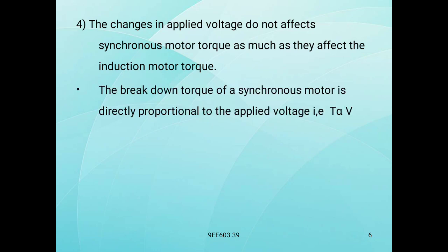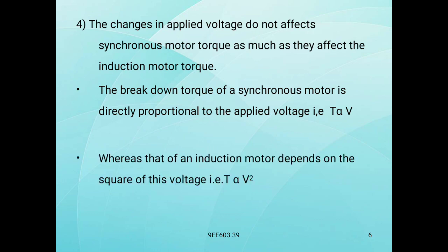The breakdown torque of a synchronous motor is directly proportional to the applied voltage, that is, torque is proportional to V, whereas that of an induction motor depends on the square of this voltage, that is, torque is proportional to V square.